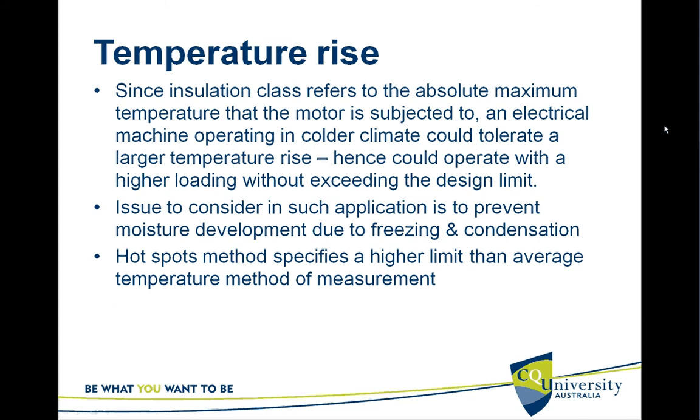Now the temperature rise. Since insulation class refers to the absolute maximum temperature that the motor is subjected to, an electrical machine operating in colder climate could tolerate a larger temperature rise, hence could operate with a higher loading without exceeding the design limit. So the environmental temperature also matters.